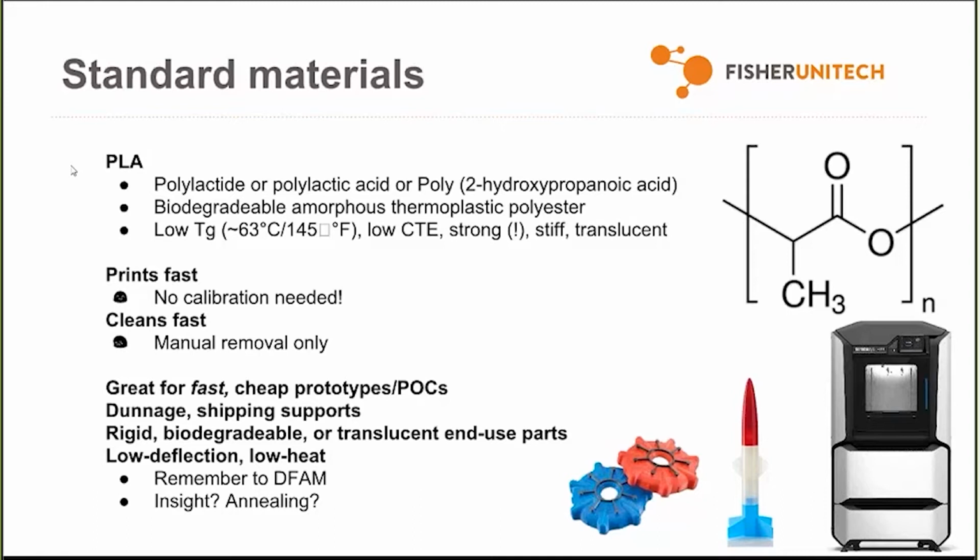And finally, if you have the skill and knowledge to design parts that don't require supports, that's the acronym Design for Additive Manufacturing, or DFAM. Well, you can use PLA for pretty much any low heat application where the part does not need to bend, because it's pretty stiff, and when it deforms, it usually breaks. It's strong, in other words, but brittle. So parts like spacers, sleeves, maybe grips and handles, that's the thing. You can build those all day long out of PLA.